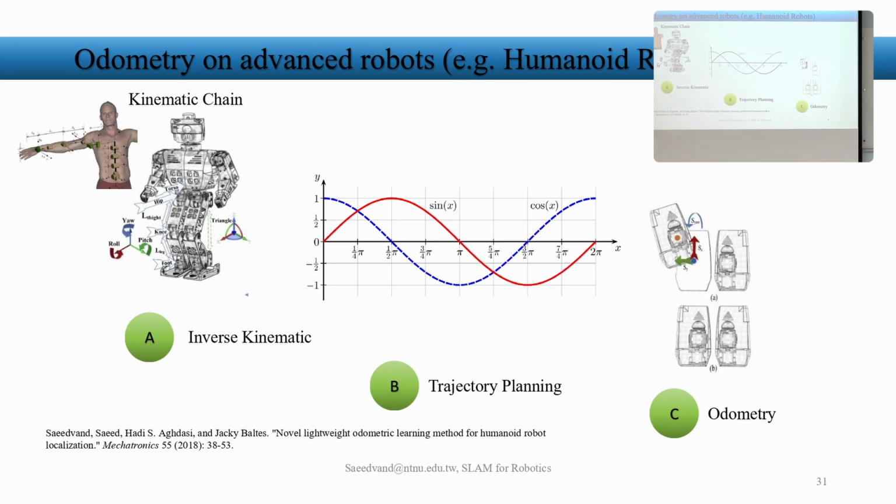For example, one of the examples. There are many approaches to inverse kinematics. If I want to briefly explain the analytic one, what happens is you write some equations. You say, I have the x, y, z of this object in the 3D environment of my workspace. Then I want a function that, if I consider my right arm's end effector, end point, and send where x, y, z I want it to be, calculates all the joint values for me. I implement that one time.